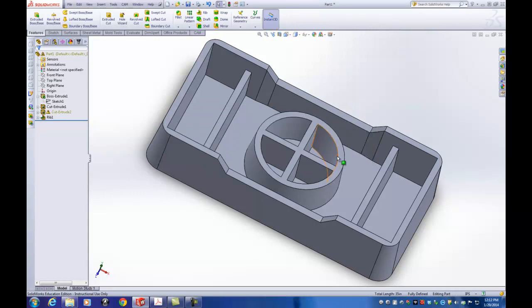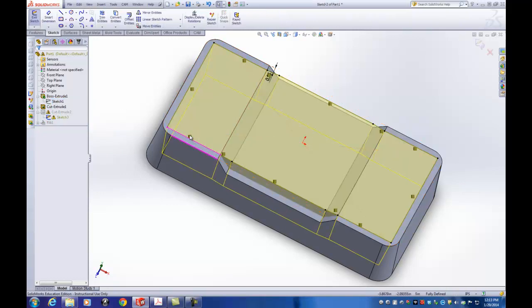If you continue through that error, then it shows you where the error is. And right here you have your yellow caution sign. If you hit the plus next to the cut, the error is actually in the sketch. So if I select the sketch and edit the sketch, these are no longer offset from that geometry because I changed that outside geometry.